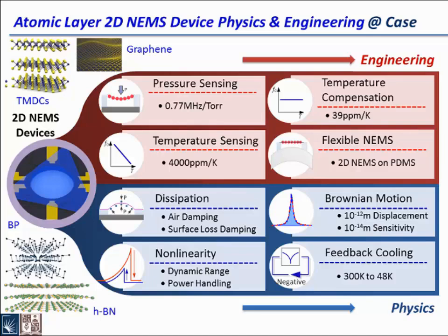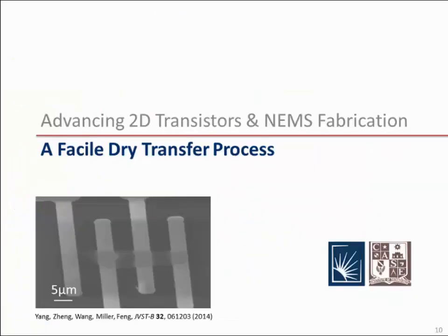Toward very growing, very rudimentary application aspects, we have been looking at pressure sensing, temperature coefficient, and then temperature compensation to make initially very sensitive, thermally very sensitive 2D devices to be thermally insensitive, depending on different needs. And also, we have made flexible NEMS devices on a highly stretchable PDMS substrate. This work was reported last year in the MEMS conference.